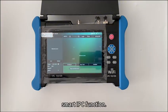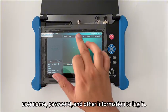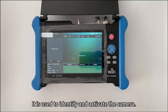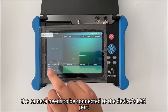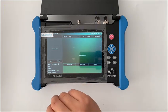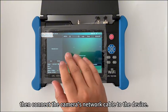Smart IPC function. In this function, connect the network cameras we need. And you can enter the ping command, username, password, and other information to log in. It is used to identify and activate the camera. Some cameras also support brute force password cracking. It should be noted that the IPC network camera needs to be connected to the device's LAN port or connect to the device via wireless network. If you need to support PoE, you need to turn on the PoE power supply first. Then connect the camera's network cable to the device.